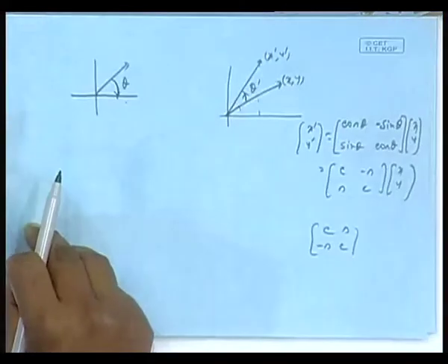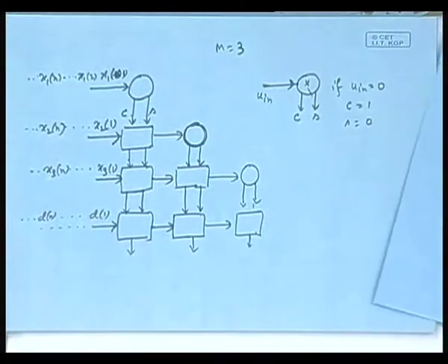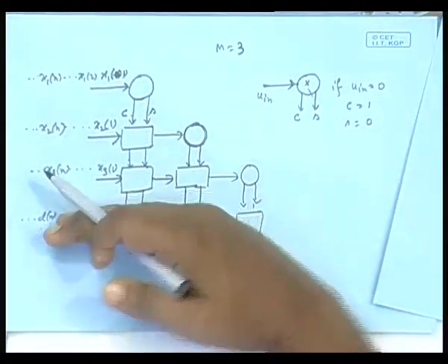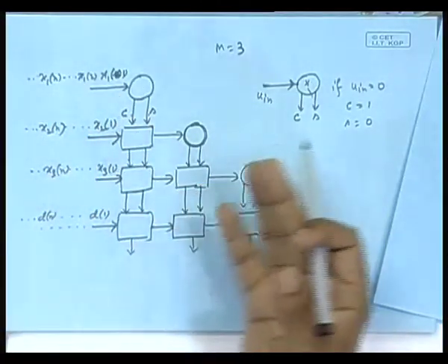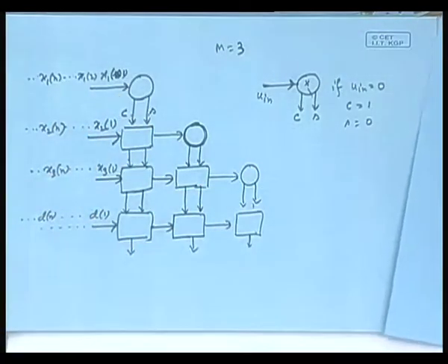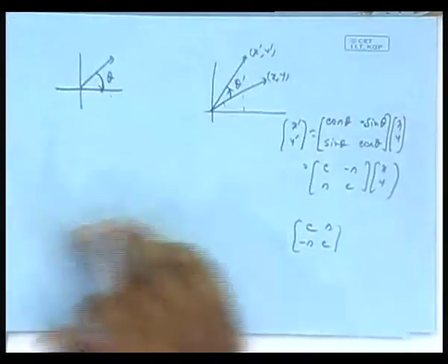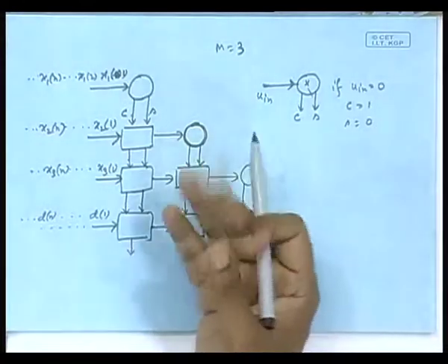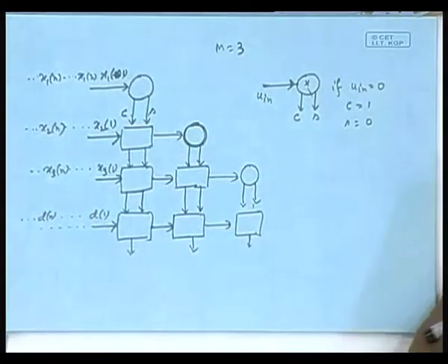Or have you forgotten? Cut set retiming you know very well. So, I can just apply cut set here, cut set here, cut set here, cut set here. Resequence the inputs and all that. About them I will tell you. That is not difficult, because there is no feedback here. So, cut set, or even if I do not use the term cut set, it does not matter.